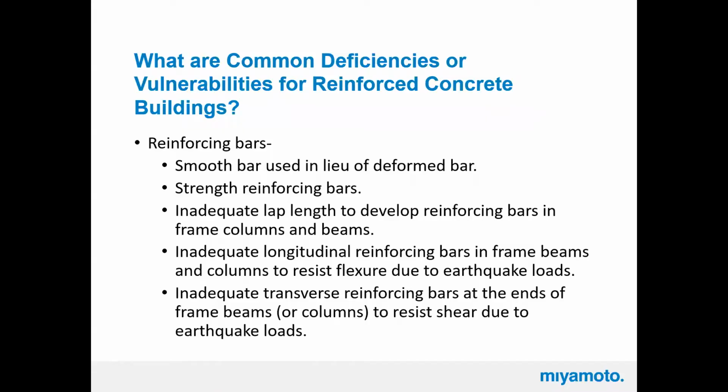Tons and tons of openings, and then relatively stiff boxes on top of that. So they're very soft at the first level and very stiff above that. That's an irregularity that just causes a lot of damage. So a lot of these buildings collapsed. It was interesting. I remember at the time, whatever direction the earthquake hit, if all the garage doors were open, then the buildings fared very poorly. If the garage doors were shut, they tended to do a little bit better because the garage door could act somewhat as a strut and tie to resist some of the seismic forces, which is kind of a small thing, but it was definitely noticeable.